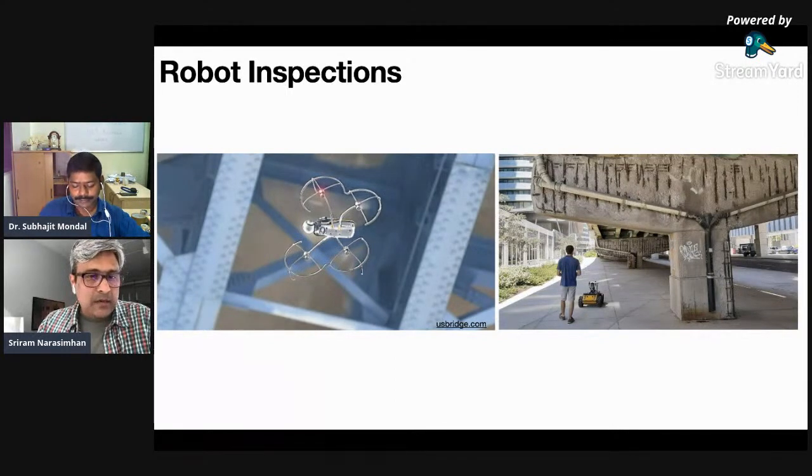So they got cameras, they got lidars, they got all sorts of really sophisticated sensors that you could just take under the bridge, and it can create a digital map of your structure, so that then you can quantify defects. For example, how much of this concrete area is lost, and how does this relate to the strength deterioration in concrete bridges and things like that.